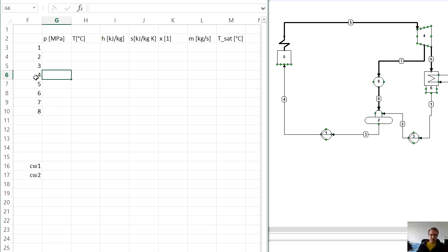In order to make our calculation more convenient, we will add some auxiliary points, and for some points we will also suggest a different notation. As you can see, we have equipment such as turbines or pumps with some given real efficiencies. So for a more convenient calculation, we will add auxiliary isentropic points for isentropic expansion or compression. Before point number 2, we will put point number 2 isentropic.